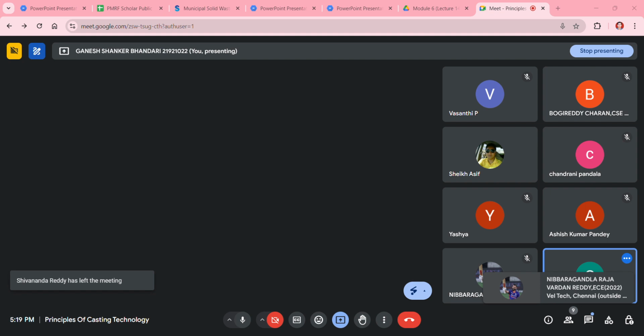That will be 11. Then UC, the container unloading time, is 0.05 hours per container. Other things we already have. NP 11 minus 1, then 0.060 plus 0.042 into 0.16. So the total pickup time for the stationary container system will be 1.22 hours per trip.